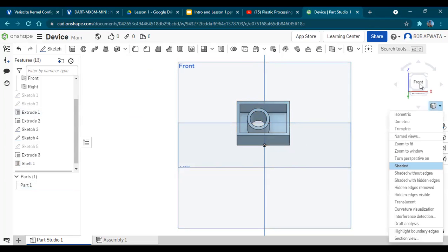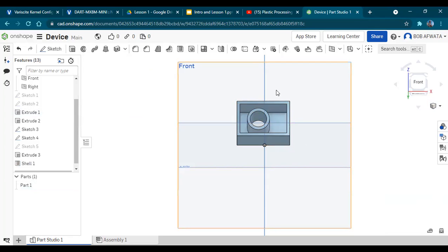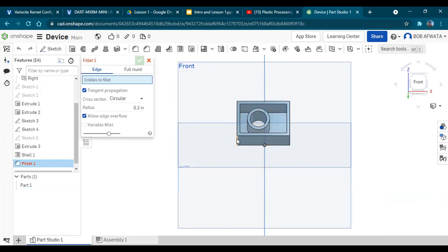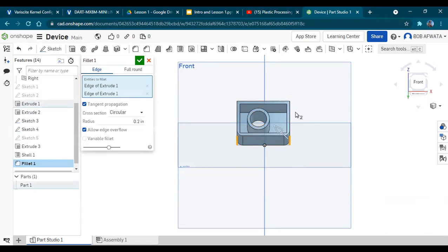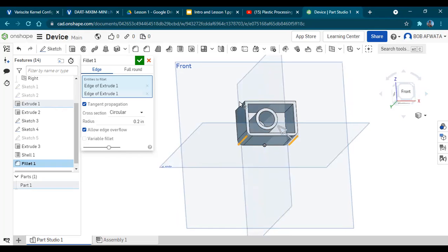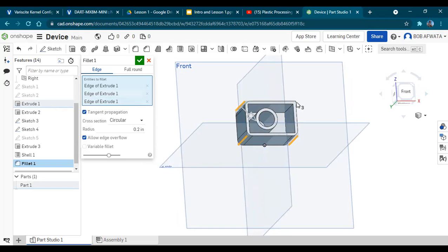It's like if you have a round box and then you shell it, now it will have a hole in the middle. Then there is also fillet, which is my favorite. So you click on the four corners. Fillet we had looked at yesterday. What fillet does is it smoothens the four corners. Like there.